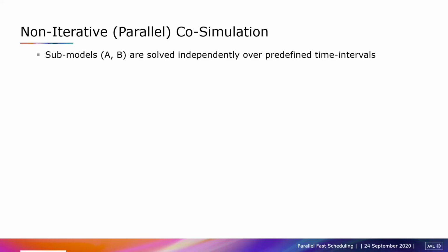Let's directly start into the topic parallel co-simulation. In our context, non-iterative parallel co-simulation. That means simulation steps are not repeated. In this case, submodels are solved independently over predefined time intervals, the so-called coupling steps.